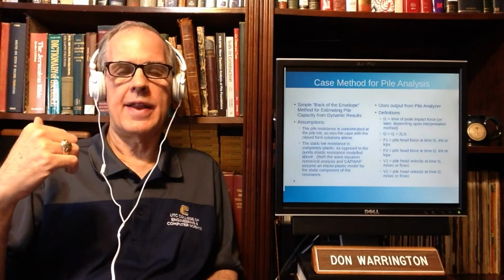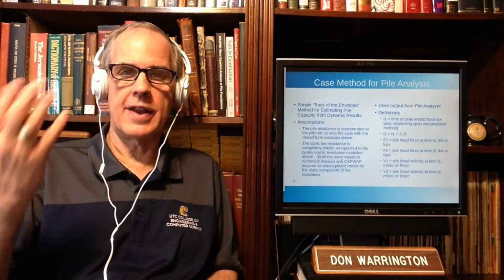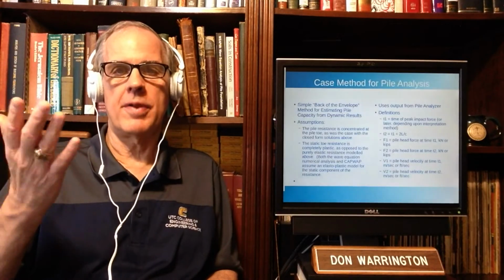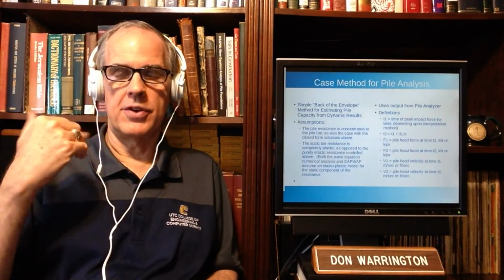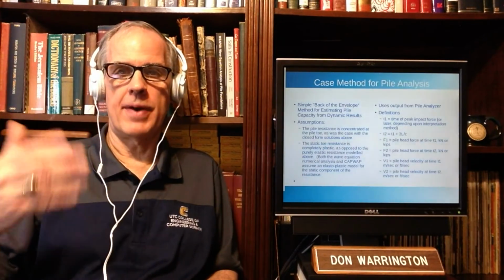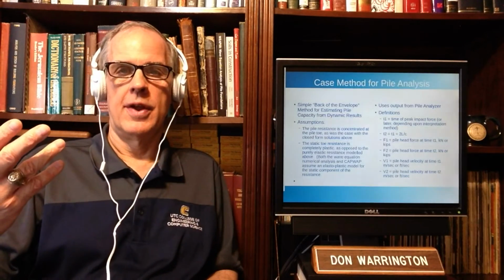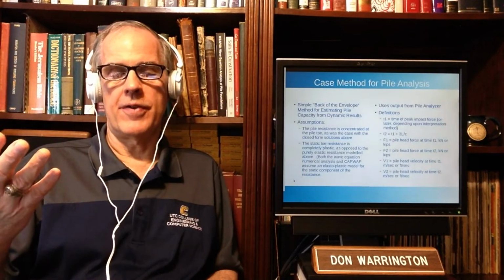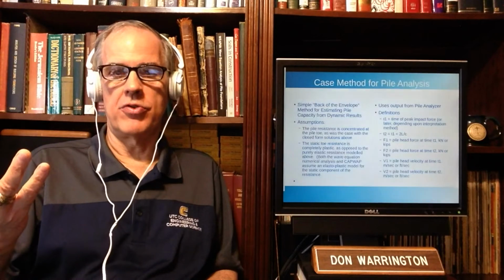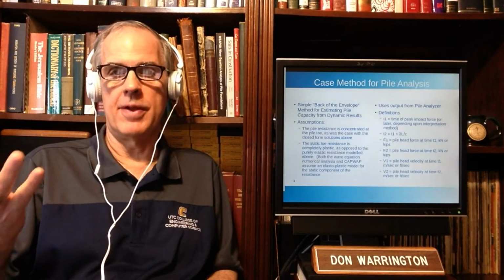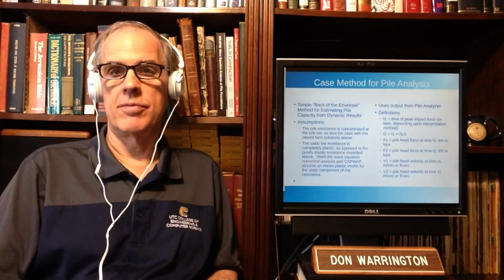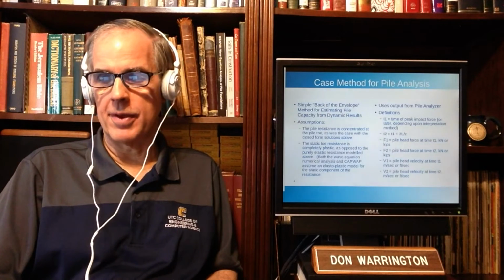It is good as an academic exercise because it's fairly easy to apply. It's good to teach people how pile dynamics basically works. But if I'm on a job, I'm going to use something like a CAPWAP or some type of method that actually does signal matching. But we're going to talk about the case method.